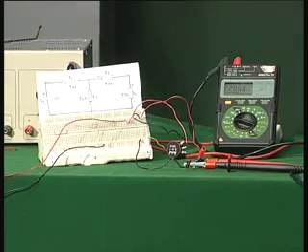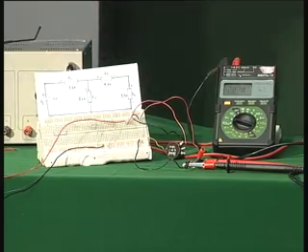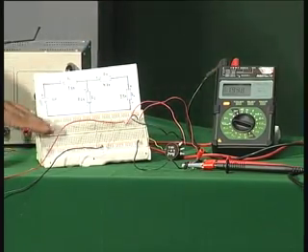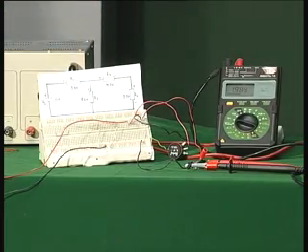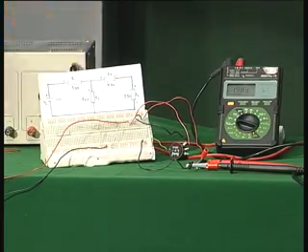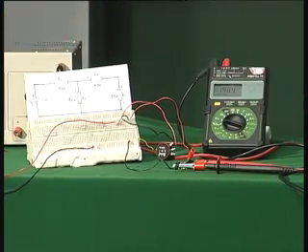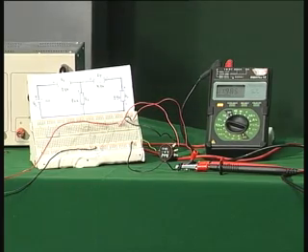There is a tolerance variation. Therefore you can see the Thevenin's equivalent circuit also gives about 2 volts. This circuit also gave 2 volts when I applied 10 volts here and then measured the voltage across the load, and therefore you can see the whole circuit can be replaced by an equivalent Thevenin's resistance and Thevenin's source, and we will be able to simplify the whole circuit in an easy way.